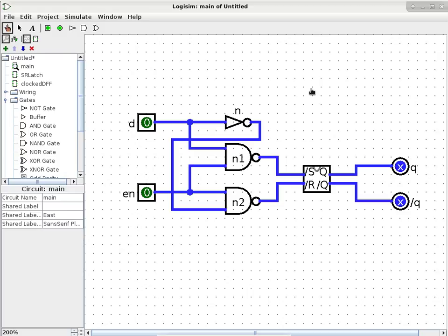First thing is the inputs are not called S and R anymore. The label S for an SR latch is really set. Okay, that's what it means. And setting means turning something into a 1, in this case turning Q into a 1. R is reset. Reset means turning something into a 0. And once again, we are turning Q into a 0.